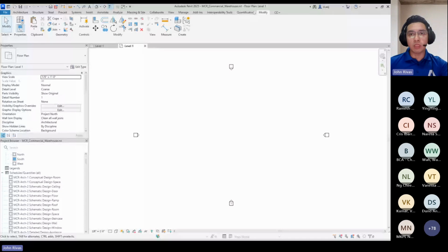So in the BCA website, you can download this Revit warehouse file, where it contains all the different schedules that contain properties related to rooms, spaces, doors, floors, etc. Right? So the step here is that if you want to populate the parameters based on a schedule, all you have to do is download this Revit warehouse file and open it locally on your machine.